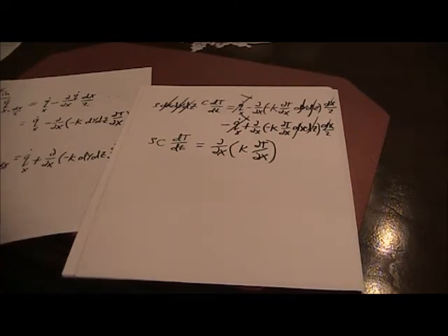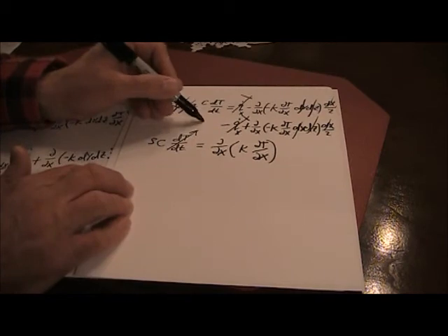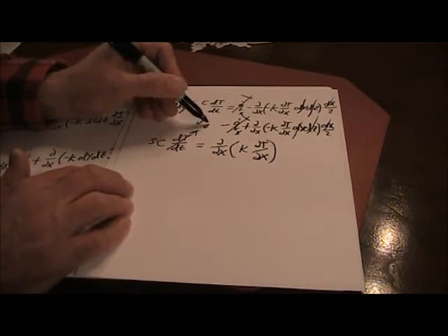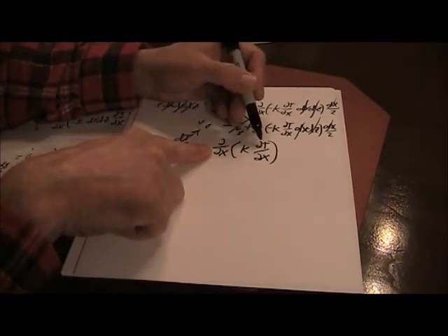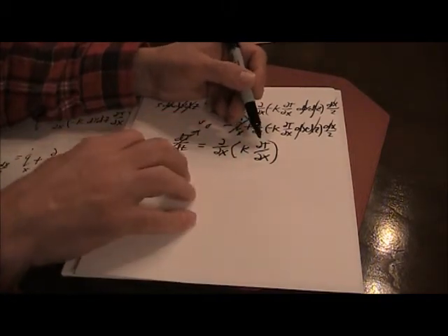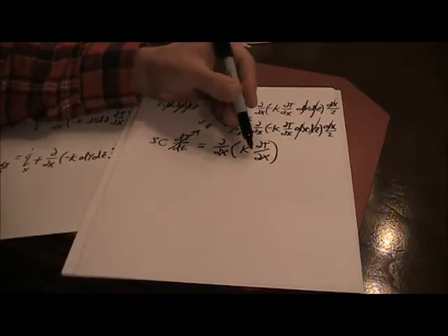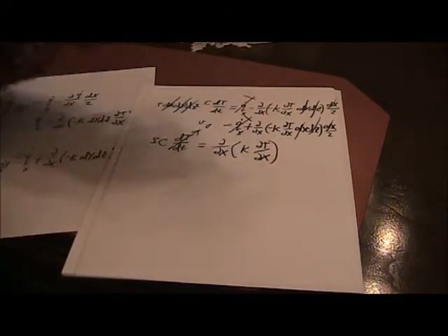For example, you can simplify this further. If the problem is steady, nothing's changing with time, so for steady, that will go to 0. And then you just have temperature as a function of one variable, so we could change these partial derivatives to ordinary derivatives. In addition, if your k is constant, you could pull that out.